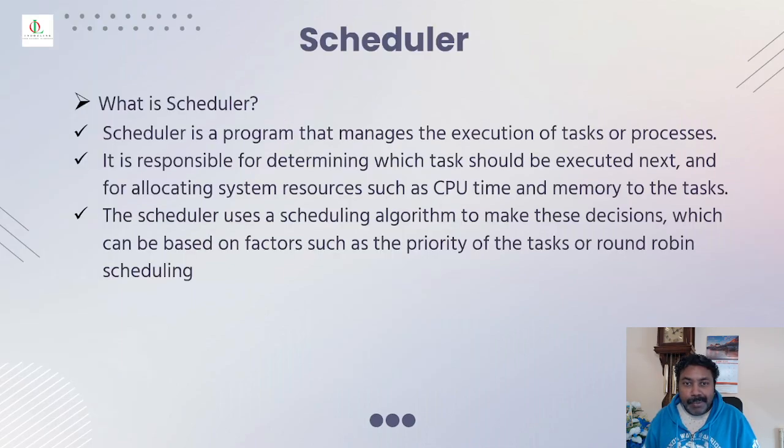First, we're going to learn about scheduler. What is a scheduler? You may know different definitions of it in different contexts, but this is in terms of microcontroller. The scheduler is a program that manages the execution of multiple tasks or processes. So in a program, when there are different functions that have to run simultaneously or one after the other, the scheduler looks after the execution of those tasks and processes. It comes in the form of a program and manages those running tasks.